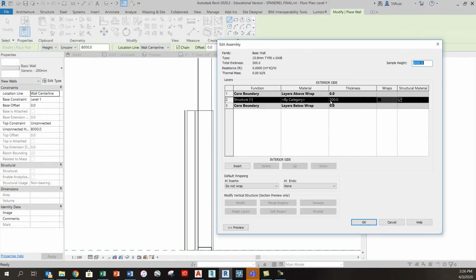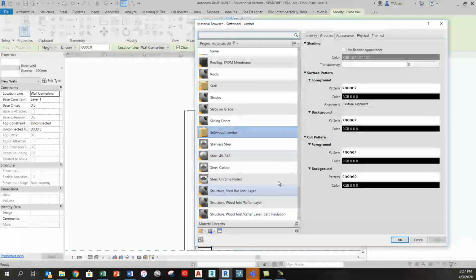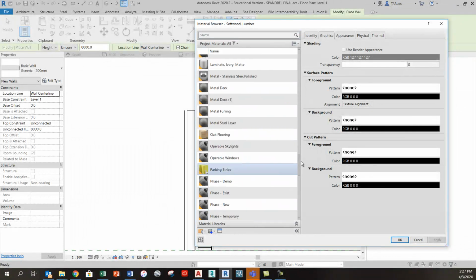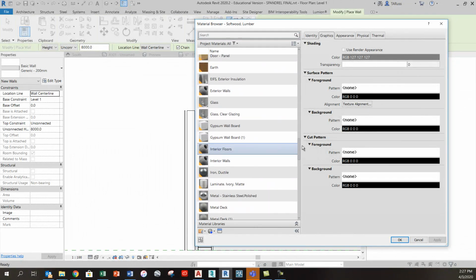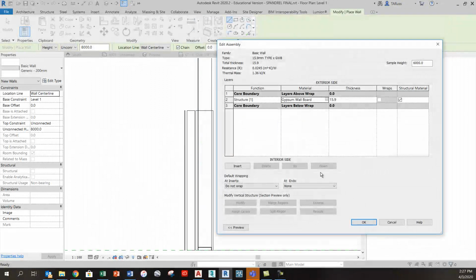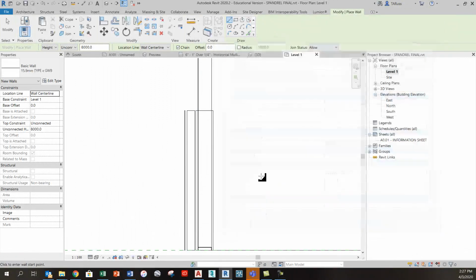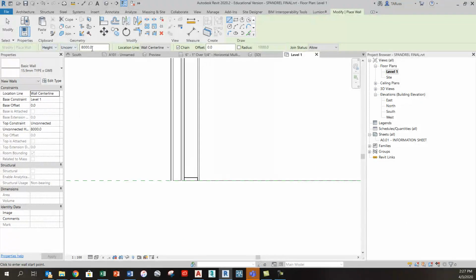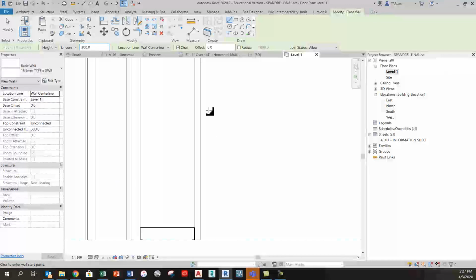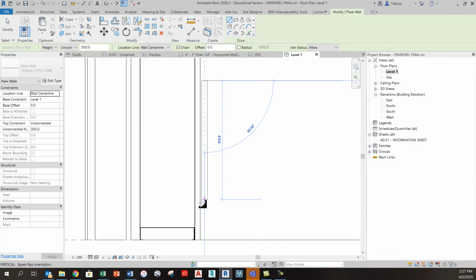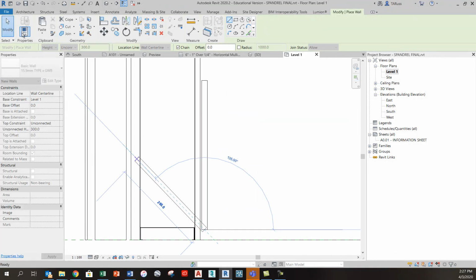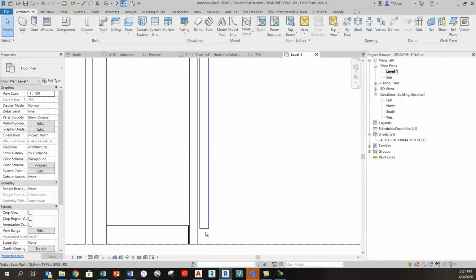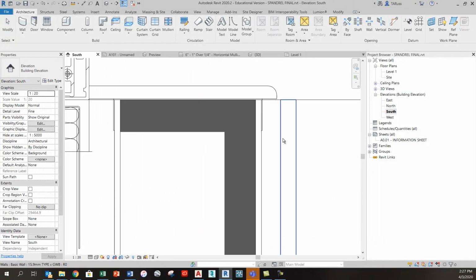And then of course I will make the changes here. 15.9, specify a material. Let's see if I've got something close to gypsum wallboard. Click OK, and then I'm going to specify that this is just 300 millimeters tall, so it fits underneath my sill plate. And I'll just place it just roughly to start, and then get a little bit more particular about the placement maybe when I go into my elevation view.